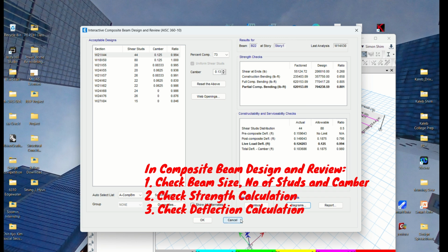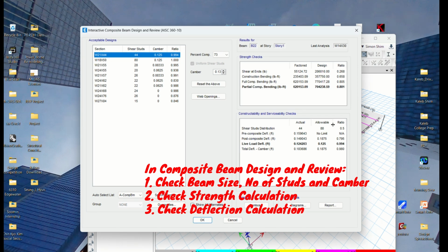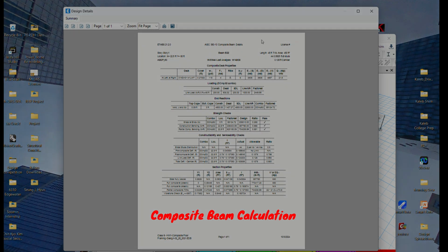Let's follow along the report and look at this moment. You should be able to double check this deflection by hand too, similar to homework 2. But you need to adjust the Young's modulus because this is a composite beam. So what you need to adjust is the Young's modulus and moment of inertia. I think they calculate it here, and you show this based upon their composite action. I think you will talk about it a little more, but this is the video I'm going to